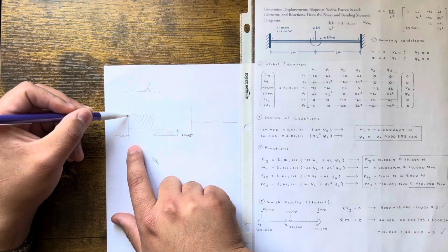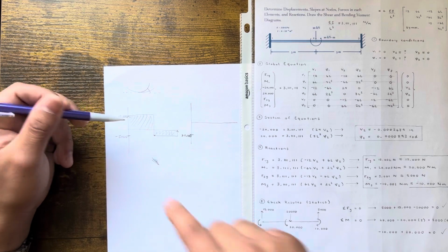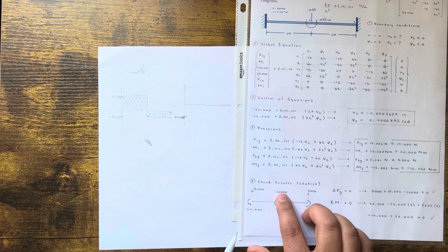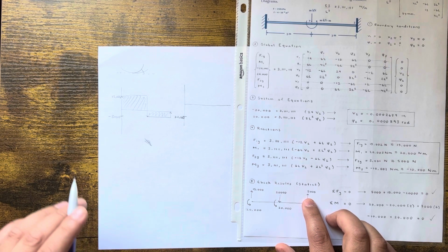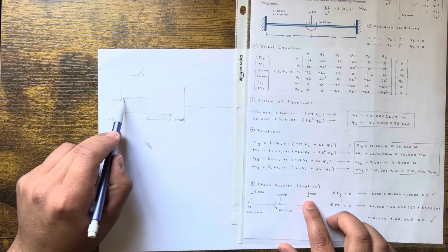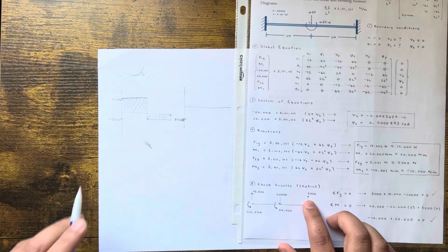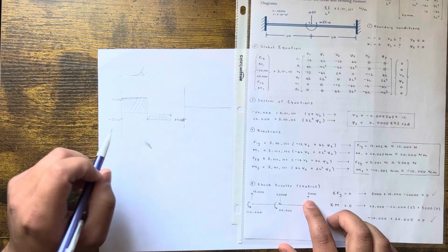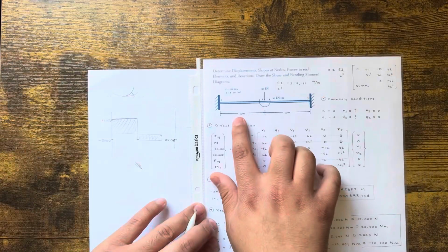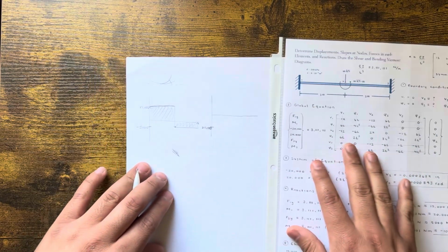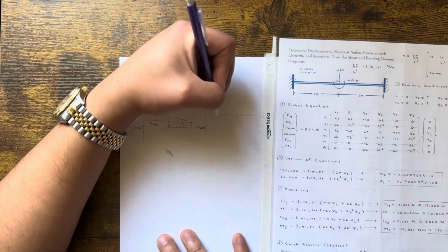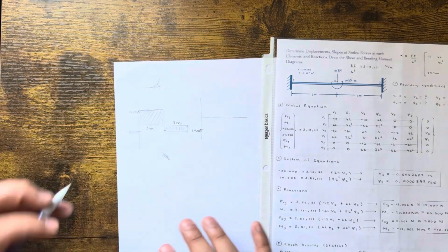The shear will create a linear distribution for bending, okay? In this case, it's a point load, right? These points, these forces, reactions, they're going to create linear distributions for shear. And they did. Then that's a linear relationship, right? Then you take the integral of that, you're going to get a triangle. So that's how you do bending moments. In this case, the distance of the total beam is 6 meters, right? So let's put that. 3 meters, 3 meters, okay? Let's just keep it like that for now.